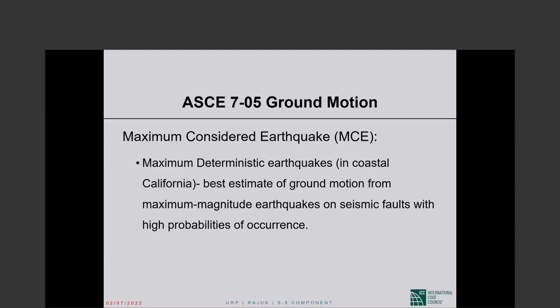Okay? Since the seismologists know, the maximum considered earthquake is the largest earthquake that can be delivered by the known seismic sources. This is also called the deterministic earthquake. In Bangladesh, you don't have to deal with the deterministic earthquake because you don't have those seismic sources capable of delivering large ground motion.